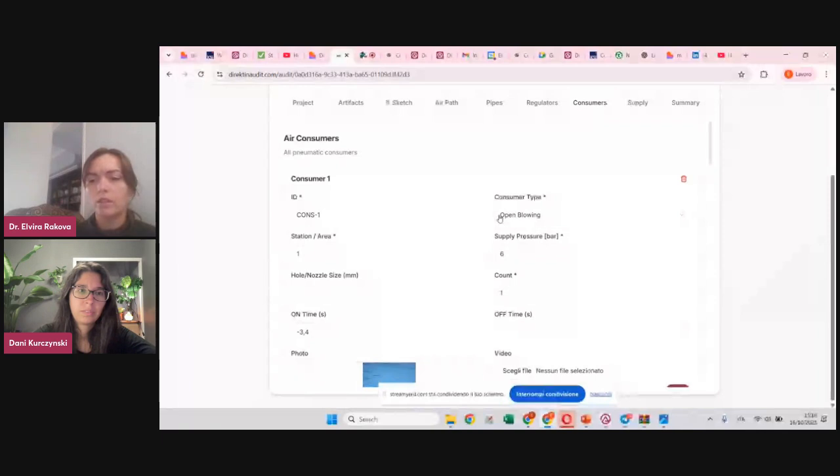It's actually not. You don't need to have all the possible connectors there, or quick couplings, or calculate the velocity of cylinders. It's not necessary in order to understand how much will be consumed, because consumption depends really on the volumes that are filled and the pressure level that is required for this application. It's important to understand what the actual pressure level for this application is, and then already to see the possible optimization.